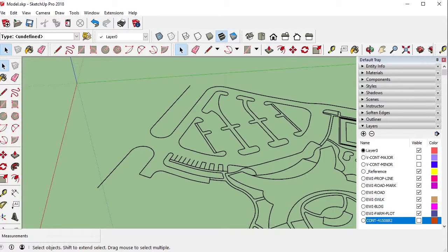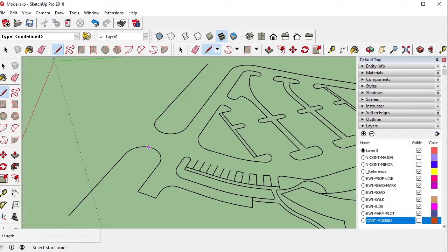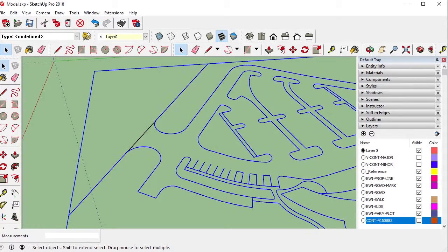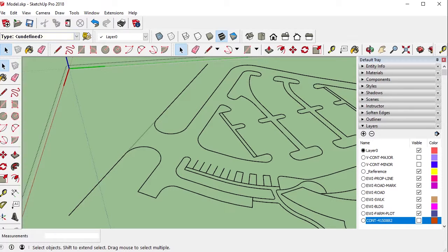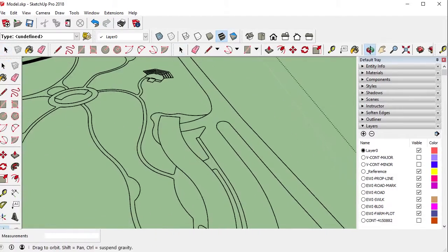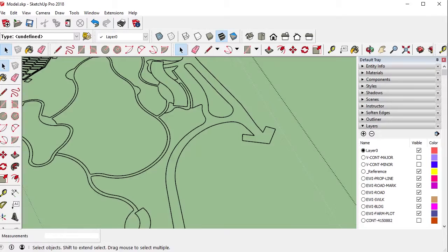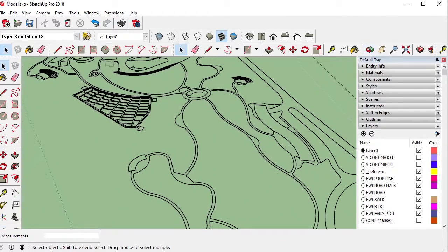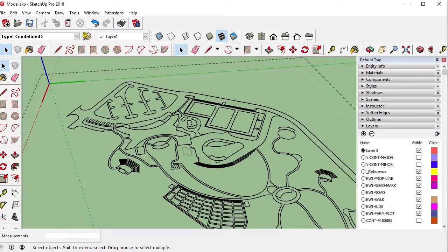So what I'm going to do is go in here. I'm just going to make a line across this. In your CAD work, hit the end point. In your CAD work, you can be a lot cleaner about the way this works. It's not in the group. Make sure it's in the group. I want to cut that, Control X, get inside the group, and paste in place. Now it's inside the group. Therefore, that's a closed area there. I'm going to look at it and see if it will fill in. In CAD, you can check to make sure all this works by using hatches. If they hatch, then we know they're going to close on these surfaces. Like I said, let's give it a go.